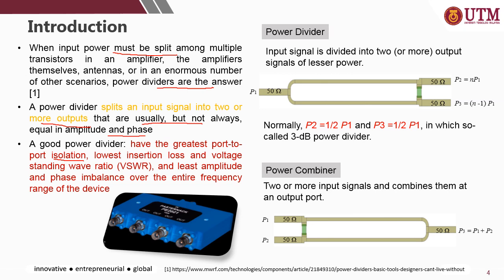And a good power divider also has the lowest insertion loss and voltage standing wave ratio, VSWR, and the least amplitude and phase imbalance over the entire frequency range of the device.